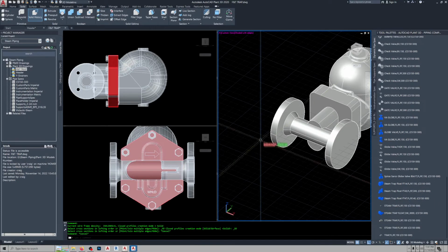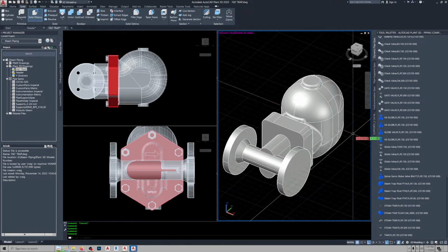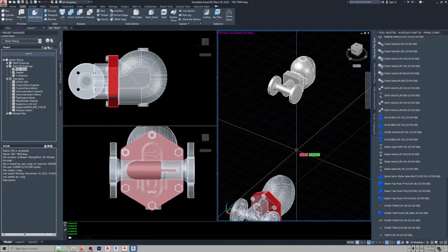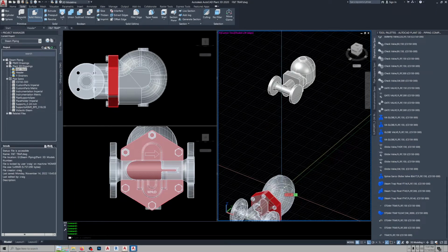The other thing that took some time to figure out is this part. What you do with this, after you get done with the front end of this, is you take your STP file, you can make a copy of it or unlock it, and explode it down until you get it down to surfaces.